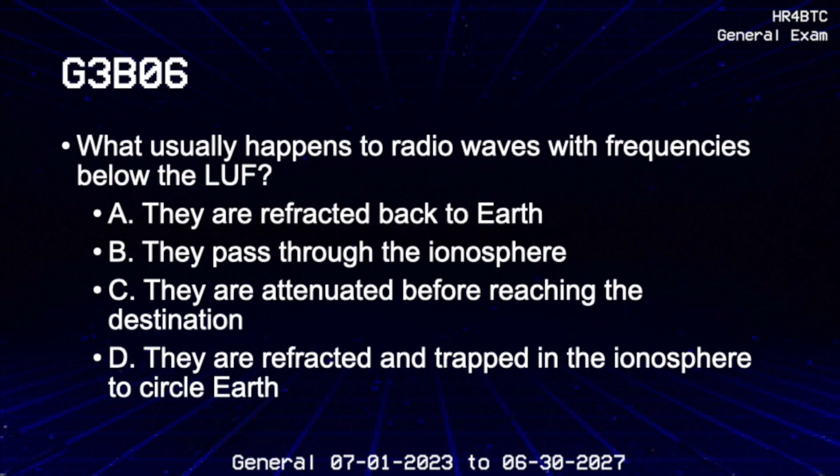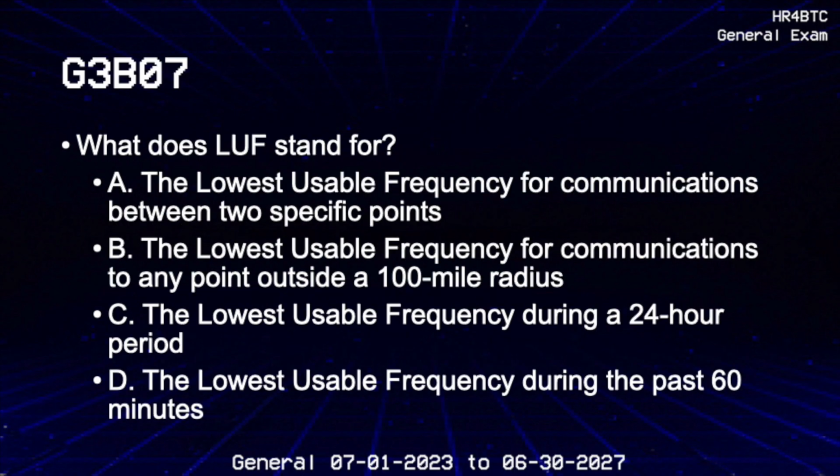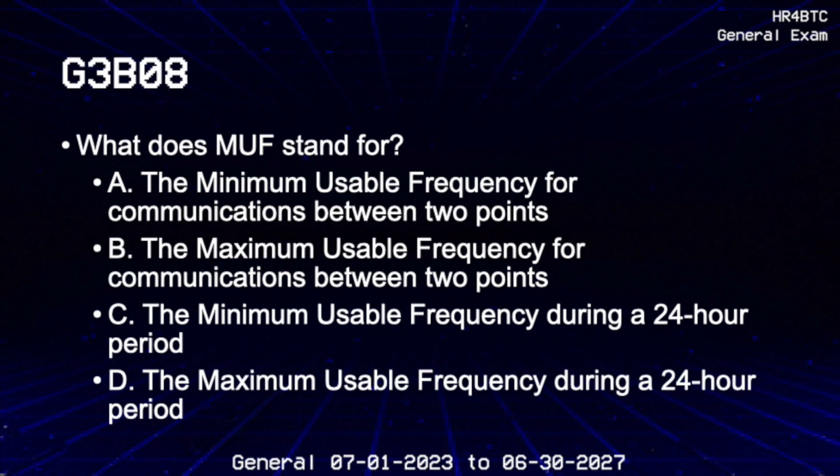What usually happens to radio waves with frequencies below the LUF? They are attenuated before reaching the destination. What does LUF stand for? The lowest usable frequency for communications between two specific points. What does MUF stand for? The maximum usable frequency for communications between 2 points.